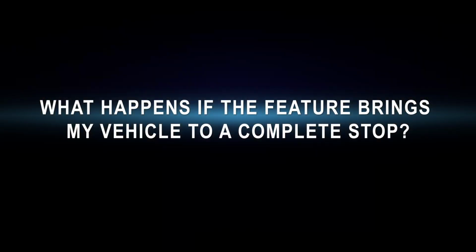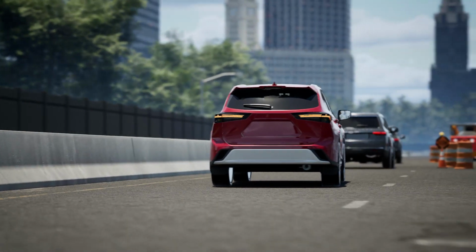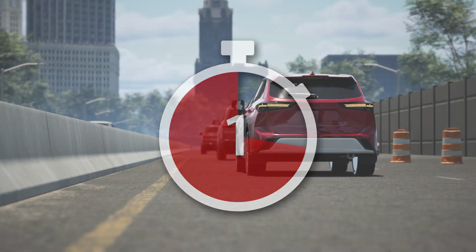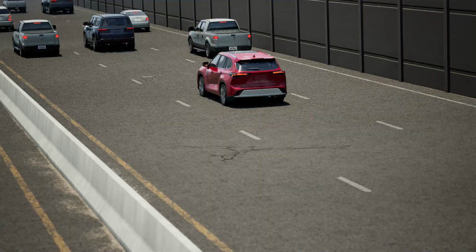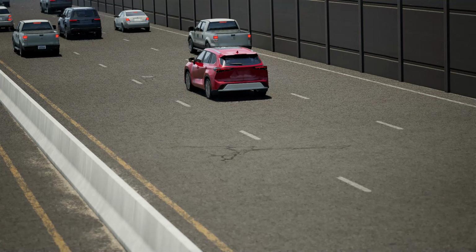What happens if the feature brings my vehicle to a complete stop? You don't have to turn the feature back on. If you are stopped for less than 3 seconds, your vehicle will resume full speed range dynamic radar cruise control automatically when the vehicle ahead starts moving. If you are stopped for more than 3 seconds, you can resume by pressing the RES button on the steering wheel or depressing the accelerator pedal.